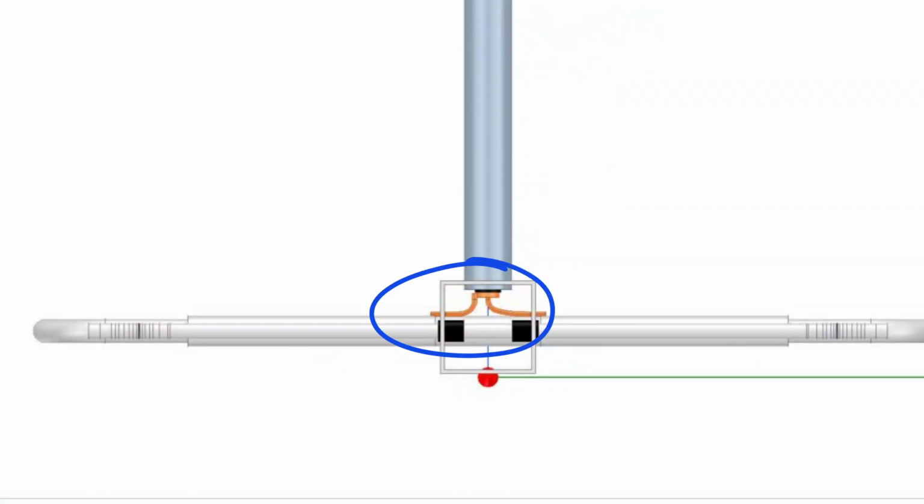RF's only going to radiate on the driven element, which is what this side is. However, with coax, the inner core is taken out, so that's on this side, but then the braid is connected to this side, but there's no definitive point to say to the RF, right, stop radiating. So of course it can just travel back down the coax, and then you get a much bigger element, if you like, on that side. Now why that's perhaps not seen so much by so many people as being an important thing is twofold really. Firstly, when you have a dipole like this and you don't have a balun in place, you're probably still going to have a good SWR.